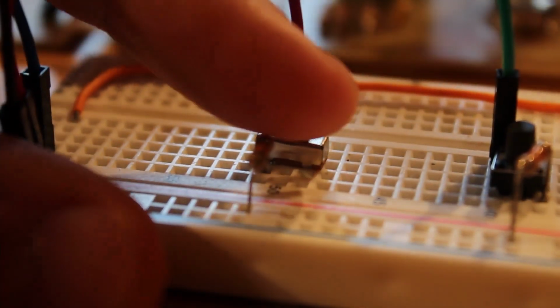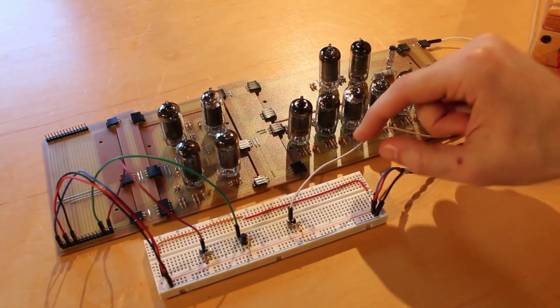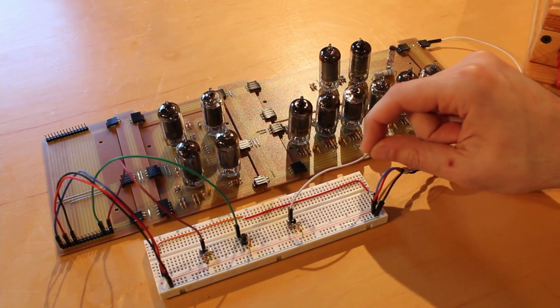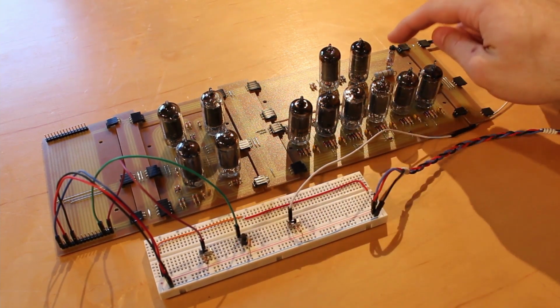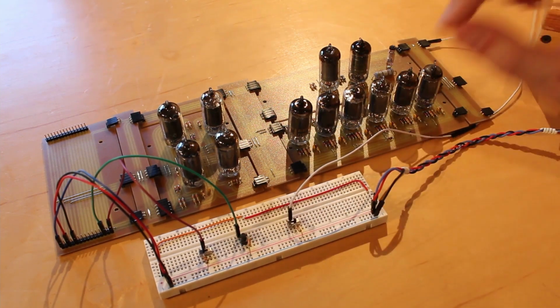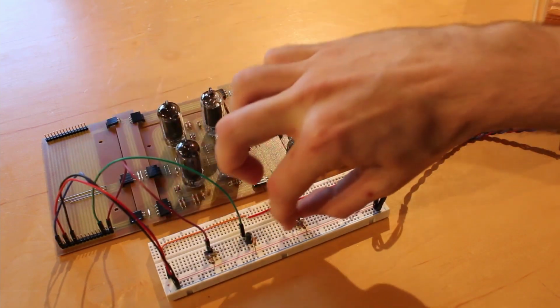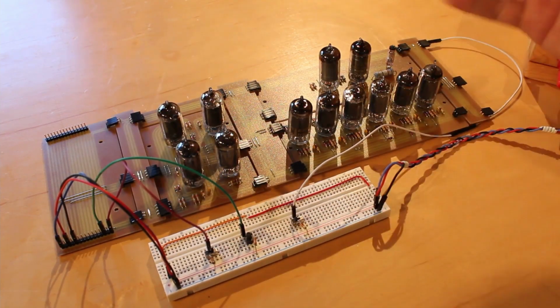Okay, so let's turn our data toggle switch on. So now we have data coming in, but our 1010 instruction from our instruction register is off. So even if I hit the clock, we should not store anything into the input enable register. Yeah, that's good. Okay, so nothing happened. And vice versa as well. If I turn 1010 on, but our data is 0, yeah, nothing gets stored in there.